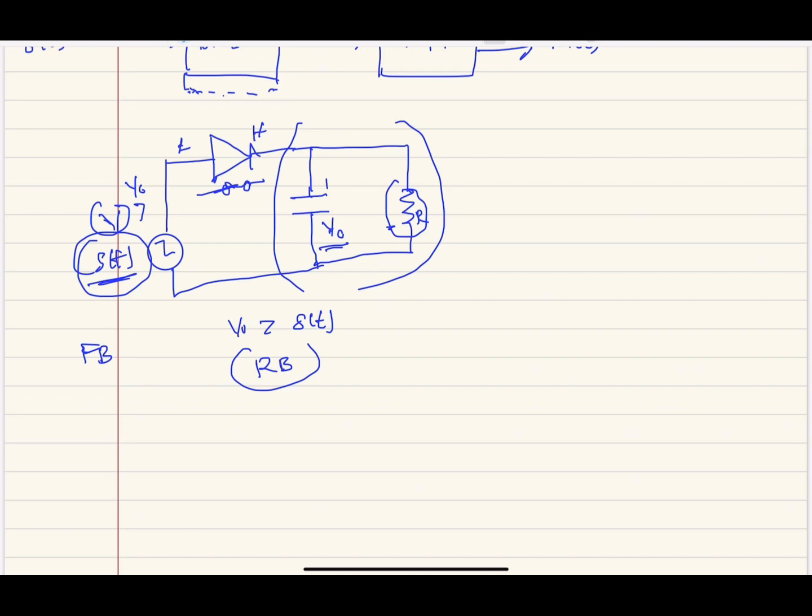If something has a time constant of, let's say, 2, and another has a time constant of maybe 5, the one with 2 will discharge more quickly than the one with 5 seconds. Therefore, you must select the components in such a way that the capacitor charges quickly.